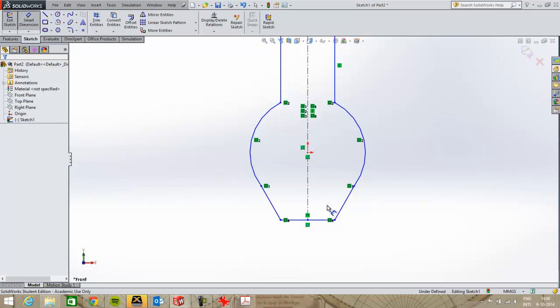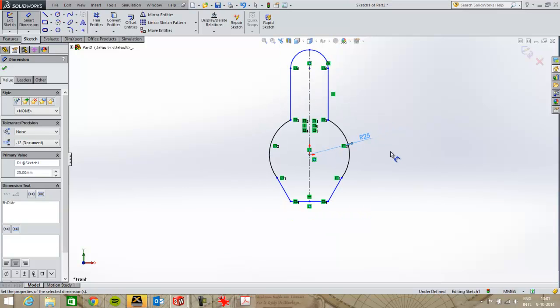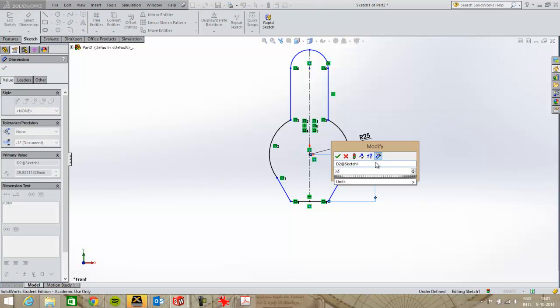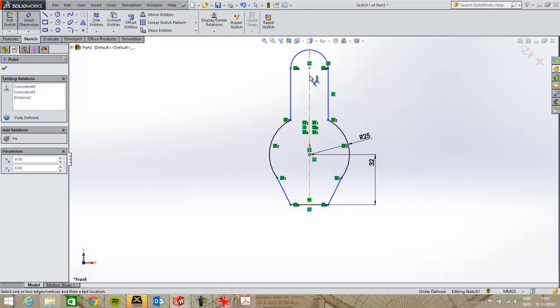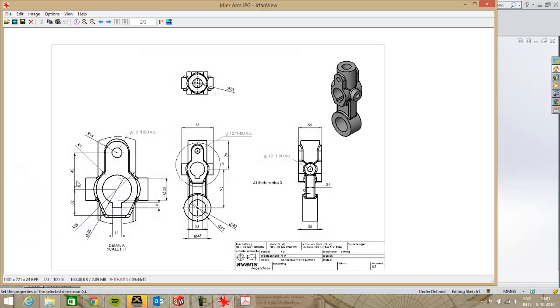So the dimensions are on the drawing, I'll use them here as well. The radius of, it's a bit of searching, the radius of this one is 25. Alright, and I'm modeling in SolidWorks 2014, so if you're in different versions things might look a little bit different, but not too much. Then the other dimensions, this one should be 33 from there to there. Yep, from there to there. 32 from this point to this point. Should be 48. So I'm using the dimensions that are in this drawing. So you see here the dimension of 48 and 33, 45 and 33 that I'm using over here.